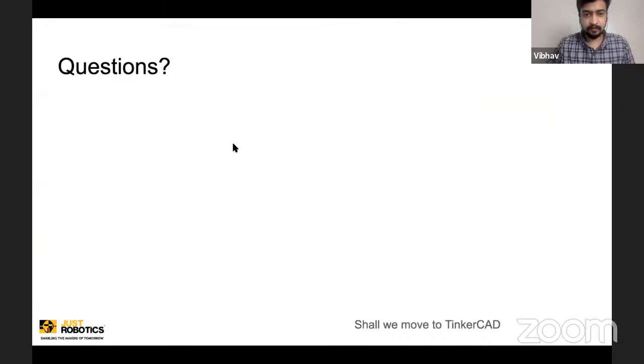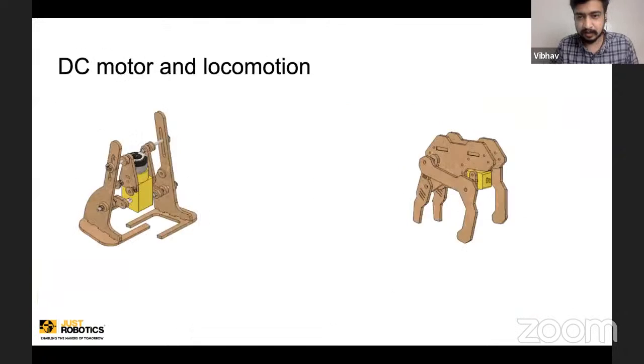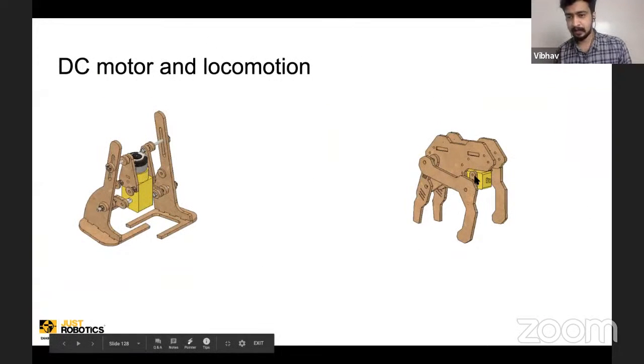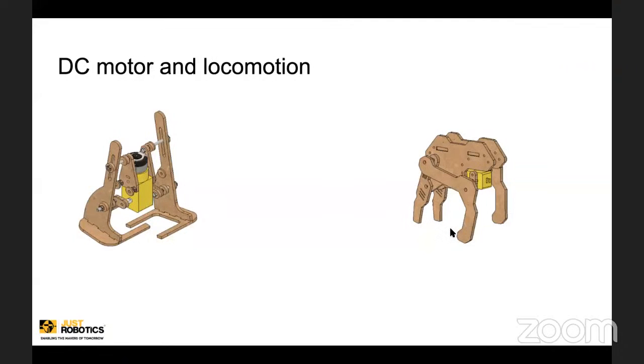Correct. So I'll tell you how we solved this problem when we built this robot. When I designed this, the offset was more. See this offset, it is almost like a cycle pedal. You are doing it like this with the motor, and the front leg is getting lifted, and now the contact points are the 2 hind legs and the left leg. The right leg is in the air. So the robot was tipping over like this.